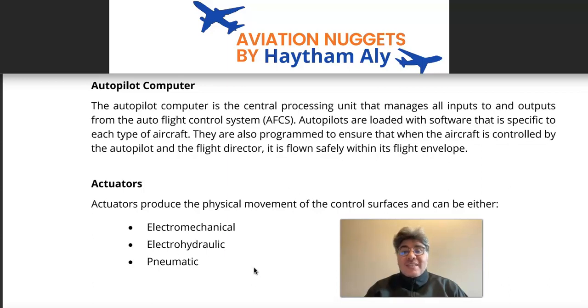What is the third component? It is the flight control unit, FCU, or mode control panel. FCU is Airbus terminology, and MCP is Boeing terminology. This is a set of rotary selectors in front of the pilot that allow the pilot to choose heading, altitude, and vertical speed. Okay, everybody. So the FCU or MCP is the short-term control between the pilot and the autopilot system.